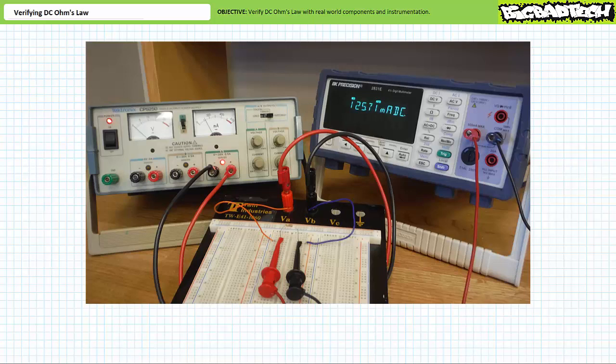If this source was capable of producing, let's say, 100 amps, all 100 amps would be diverted through the ammeter installed in such a fashion. This is a surefire way to destroy the device and those in close proximity.